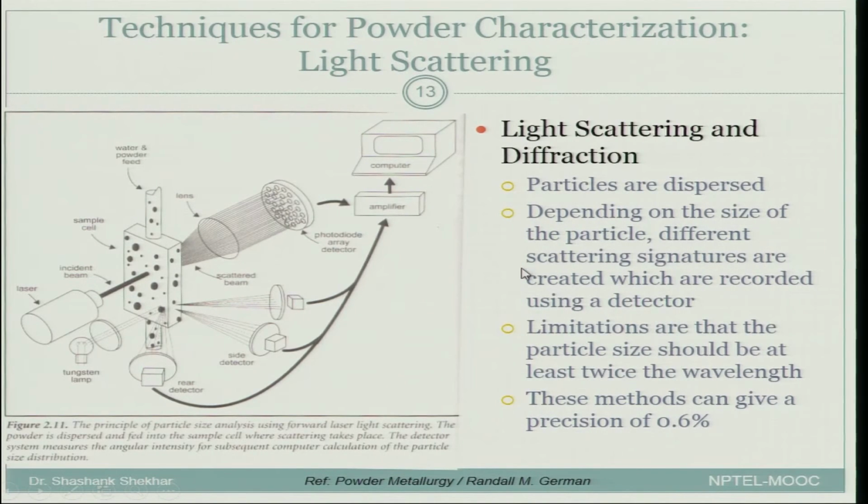One of them is what is described here. It is a light scattering and diffraction technique. So, here is a cell into which you feed the particles along with some fluid. Now, depending on the particle size and particle morphology, there will be different amounts of scattering, and that scattering is captured by a photodiode array over here and some more side detectors that you see over here.